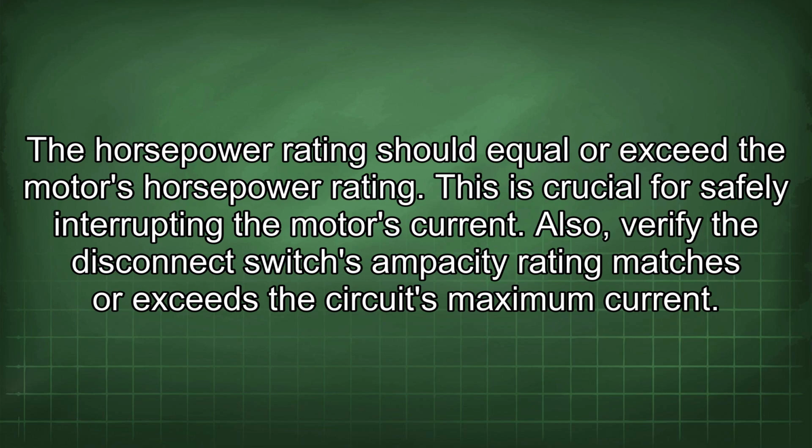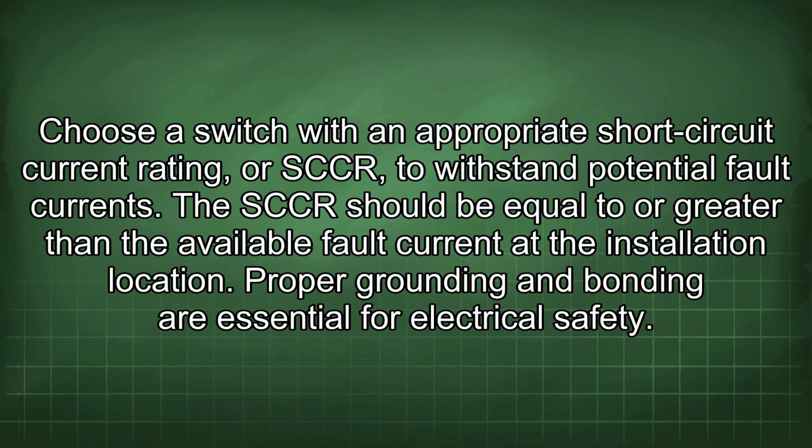Also, verify the disconnect switch's ampacity rating matches or exceeds the circuit's maximum current. Choose a switch with an appropriate short circuit current rating, or SCCR, to withstand potential fault currents. The SCCR should be equal to or greater than the available fault current at the installation location.